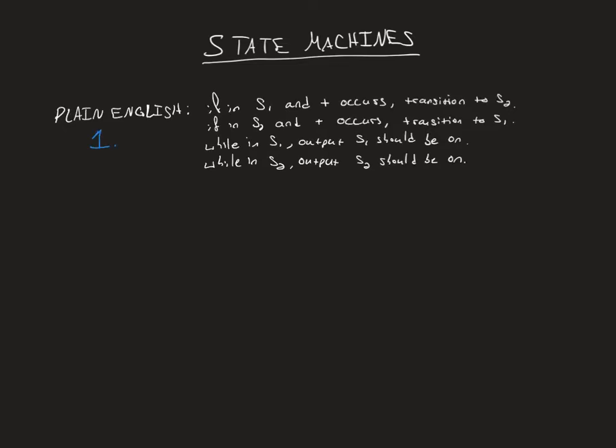Now, the next step is to define each of our states, inputs, and outputs. So, states, we will have state S1, and we'll also have state S2. All right, inputs. Well, we said that the only input we're going to have is T for transition, so T. I used an uppercase T over there and a lowercase over there, so we'll make that hybrid.